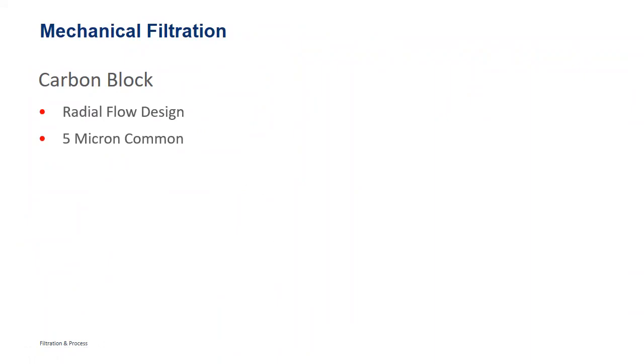Our water softening systems and backwashing carbon systems are there to do other things, but we backwash them to get the dirt load out of them. They're essentially 40 micron filters, but they still collect debris. So every filtration device used today is a mechanical filter, whether it's there for chemical removal or not. It's still going to act as a mechanical filter. That's why we put cheap sediment filters in front of our carbon filters.